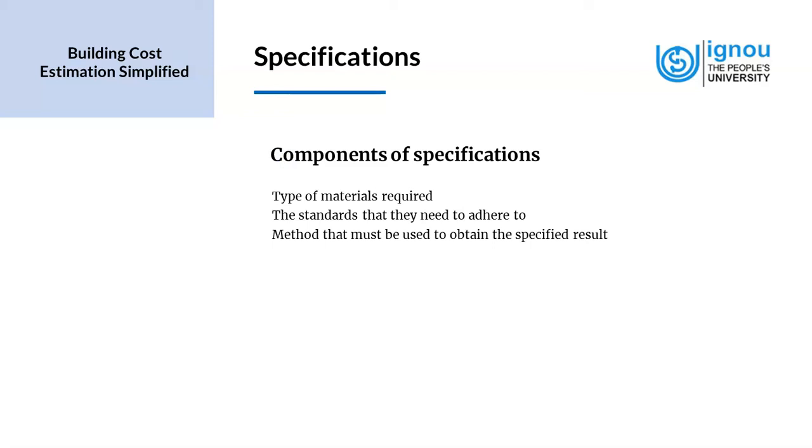We know that drawings provide information regarding how the structure is to be constructed or installed, and the specifications give information about the quality of materials, workmanship, and other technical requirements. For example, differentiating Portland cement and pozzolana cement is done better by communicating it through specifications rather than through drawings. The quality of bricks, which is normally assessed by strength and finish, can also be better communicated through specifications instead of drawings.